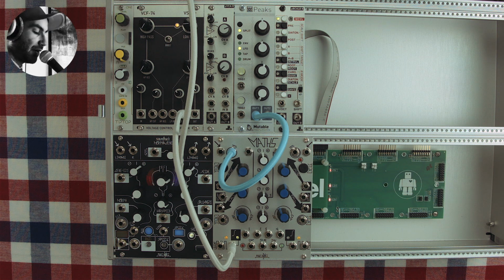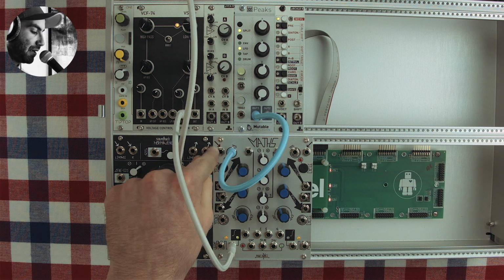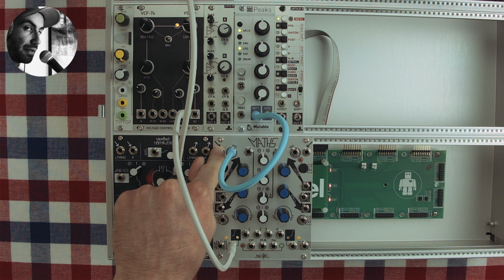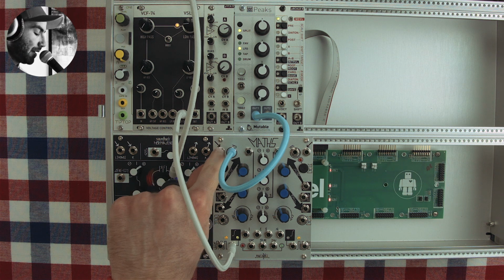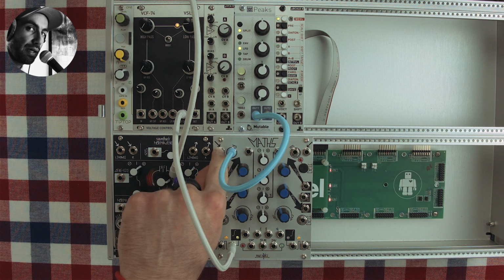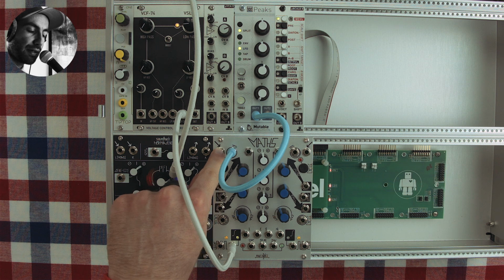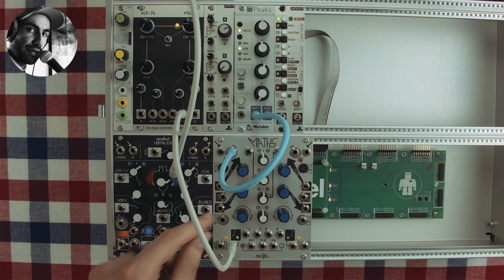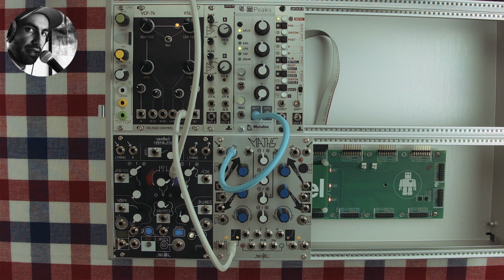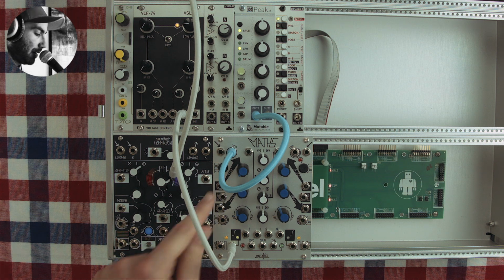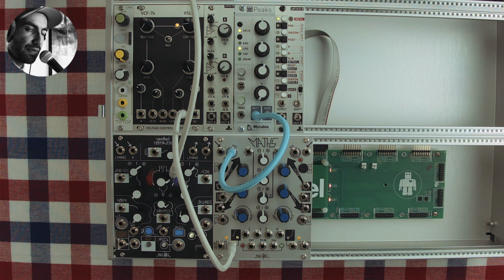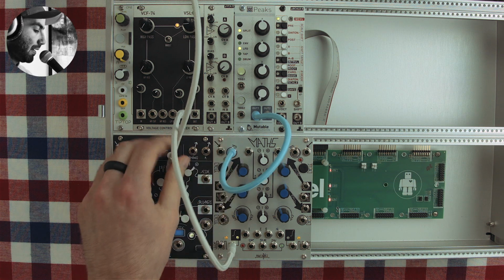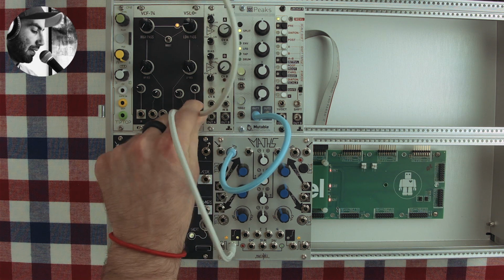But one way we can get around that is by patching our same LFO into the signal input here. And the signal input, depending on where the signal is going, either rising or falling, it'll be attenuated by the rise and fall here. So for example, if you feed a signal, an audio or a CV, and the voltage is going up, the rise time will determine how much that gets slowed down. And similarly for the fall time for when it's falling. So again, I can feed my gate input into the signal instead.